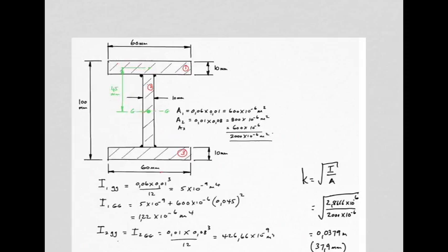Next step is to consider area 1, which is this rectangle as discussed, and determine its second moment of area about an axis passing horizontally through its own centroid. Now its own centroid is going to be denoted with lowercase g's like that. And remember, for a rectangular shape it is BD cubed over 12, breadth times depth cubed over 12. An easy way to remember it is B is this way, in line with the axis that you're dealing with, and D, the one that gets cubed, is perpendicular to the axis that you're dealing with.